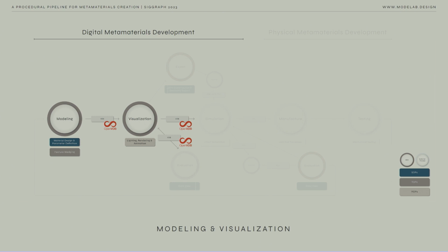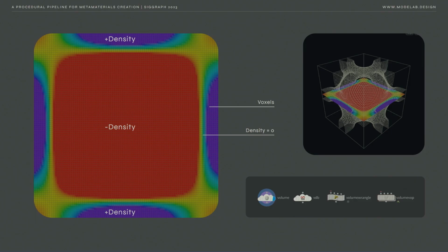But the way that we build surfaces for tooling applications or conventional manufacturing is fundamentally different than when you're talking about additive manufacturing, right? It's a different technology of make, and it requires different ways of modeling in order to be able to work with it effectively. One of those technologies that we use is, again, OpenVDB, and the underlying concept behind OpenVDB is something called fields, and these are represented typically through voxel forms as something called a volume.